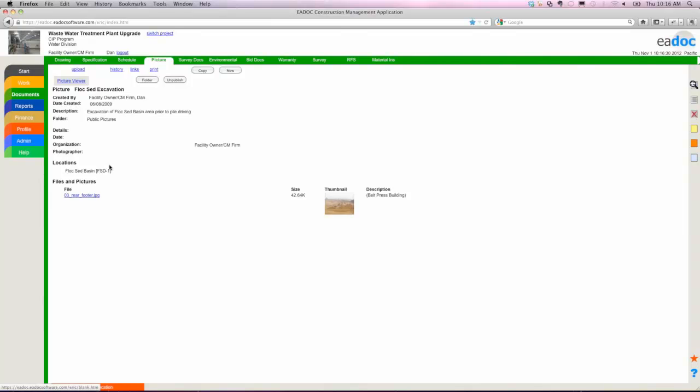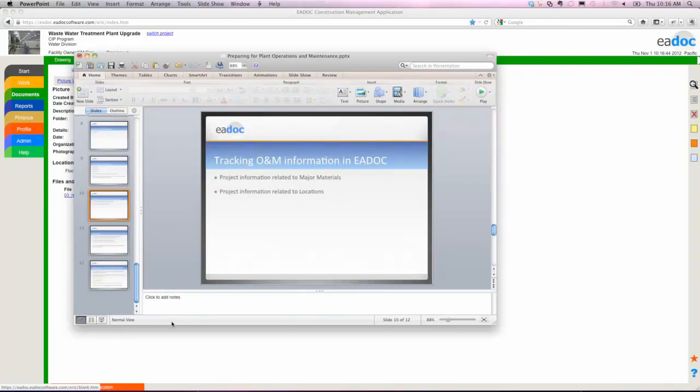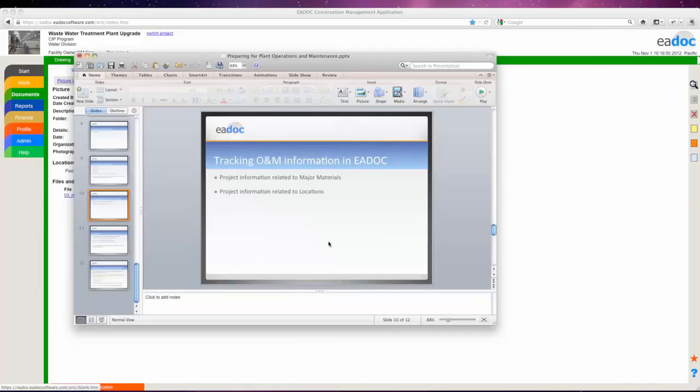So what structure should your information be in as it goes through a design phase, and what data are you capturing? So you're identifying those materials during your design phase. COBIE's telling you how to identify those materials, how to set up that tracking mechanism. Then it says as you go through construction, how should you track warranties? How should you track O&M manuals? How should you track test reports related to these major materials?